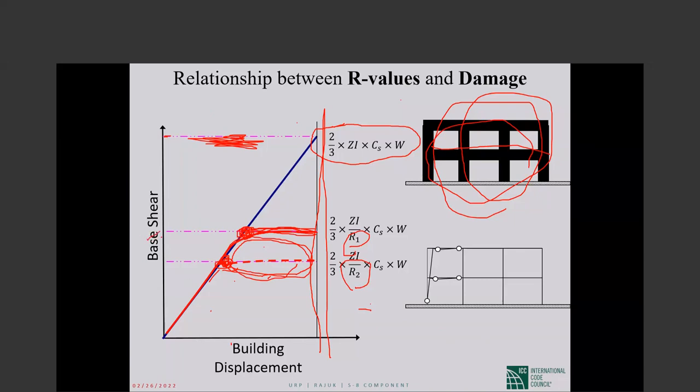You should provide lots of capacity at the points that get damaged. Very good detailing. It's not easy for a reinforced concrete section to get damaged, the reinforcement yields, there are cracks, the stiffness is zero, and still it keeps the level of loading that it was handling before. It's lots of detail.